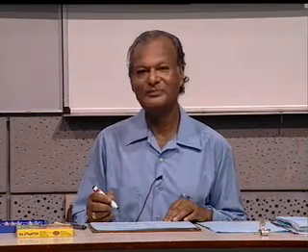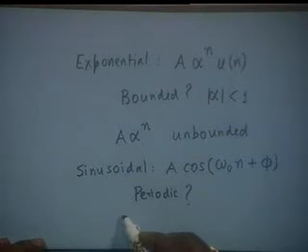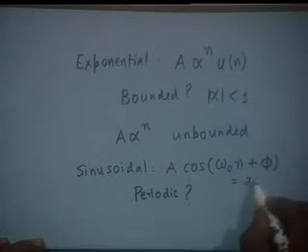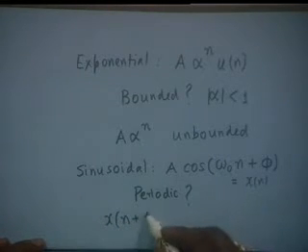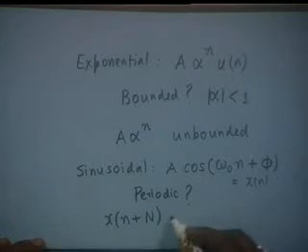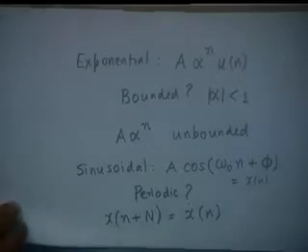So, it is a bounded signal. Is it a periodic signal? Periodic, the answer is not an unconditional yes. It may be periodic, it may be non-periodic. If it is to be periodic, then if we denote this by x of n, then there must exist a quantity capital N such that x of n plus N is equal to x of n. Agreed? Let us test whether it is periodic or not.